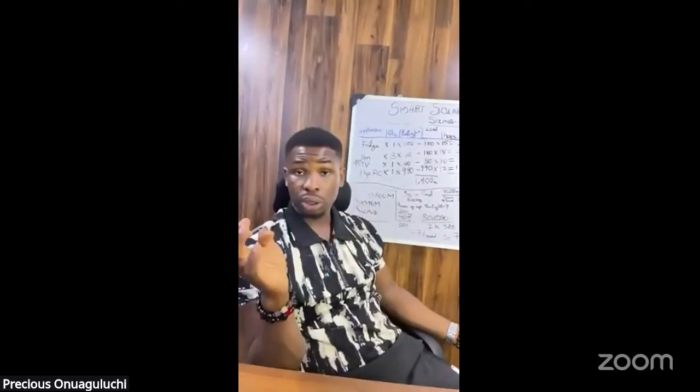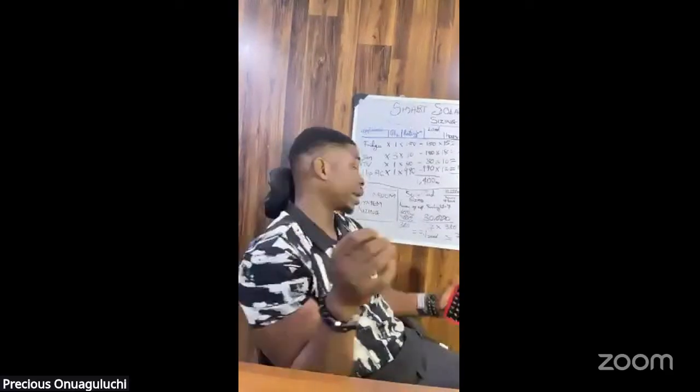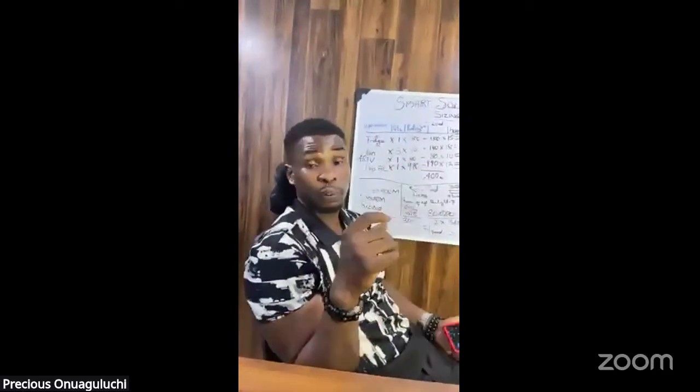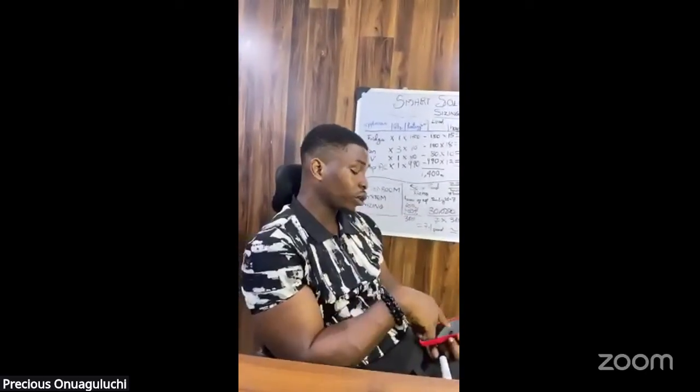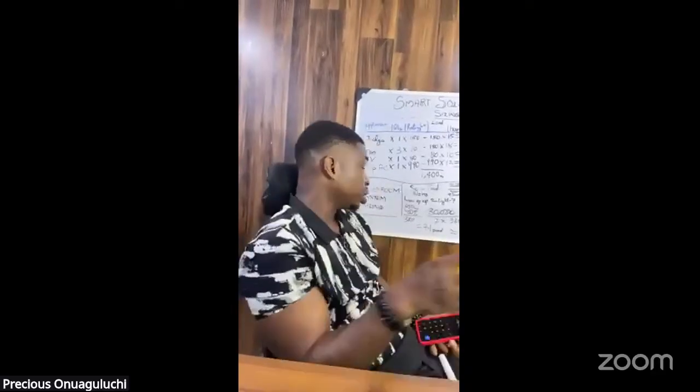So to factor in all of this, I assume that there's a 40% loss in panel generation, and I work with 60%. So whatever panel you're using, if you're using 700 watts, you calculate 60% of 700. And if you're using a bigger panel size, you calculate that.